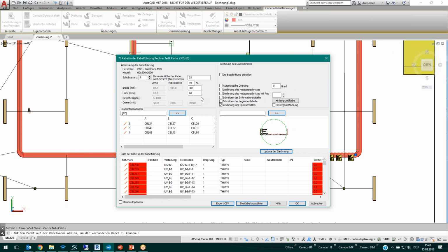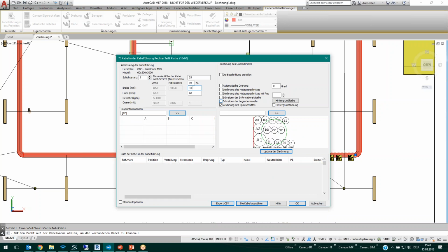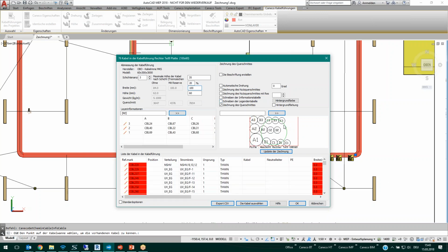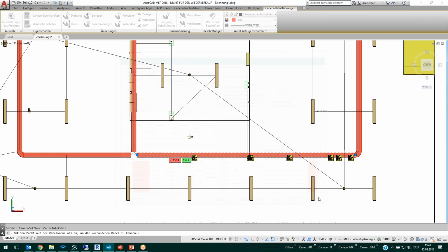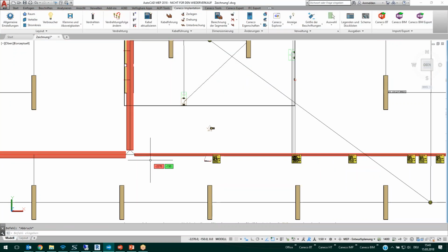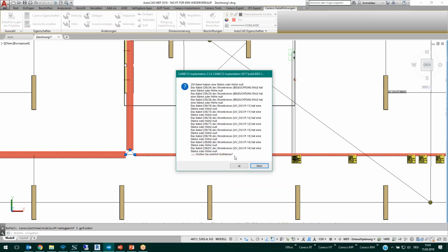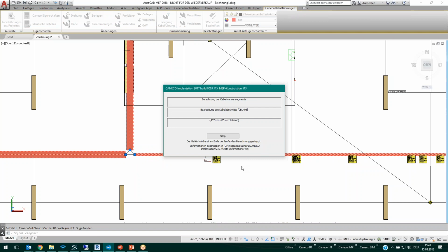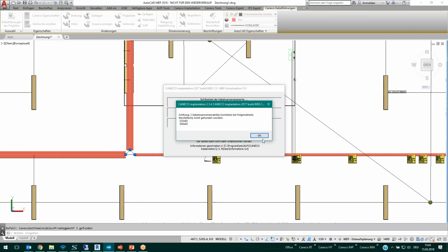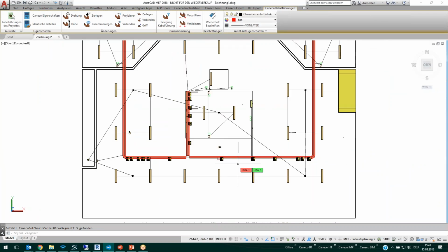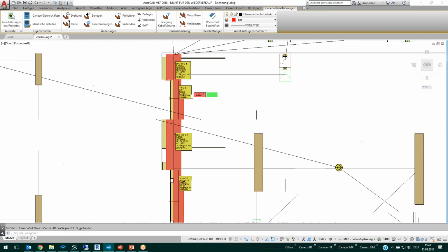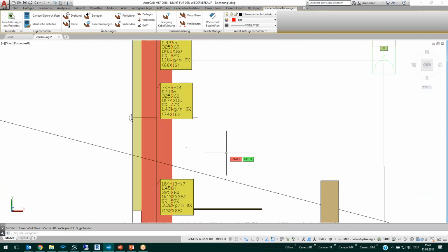So that means I can say I want to have, for example, just 100 cable tray, and I want to actualize my cable trays in this way if I want. Or I say, complete the whole project and give me what size is needed from the manufacturer, like Obo Bettermann, like everything. And he will size everything in the right dimension and give you on every step the kilogram of the cables.